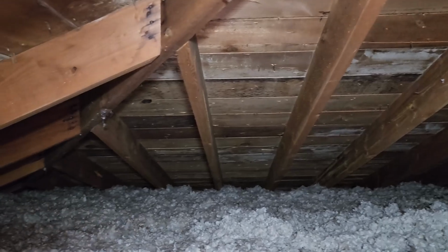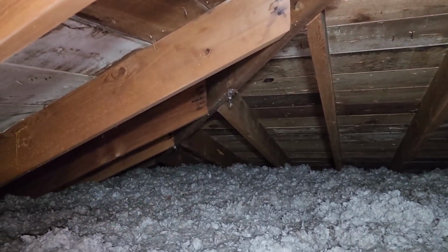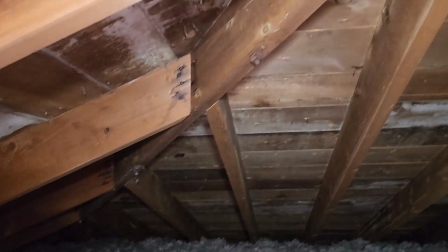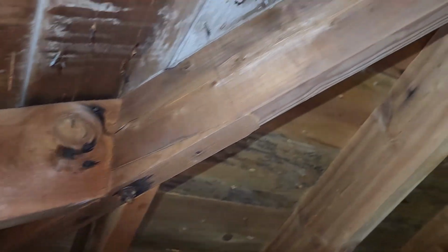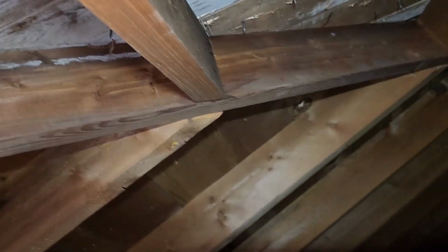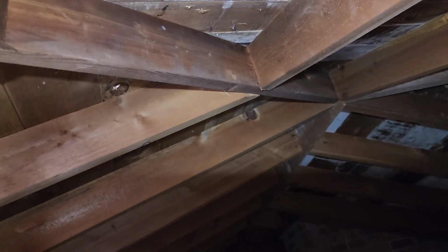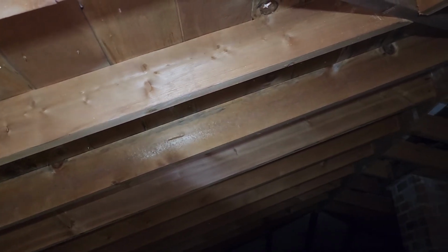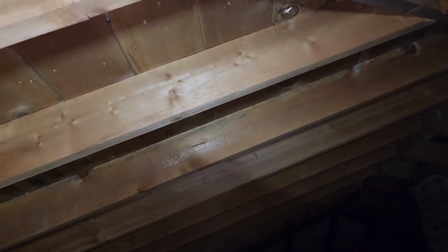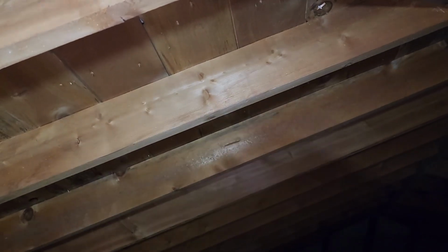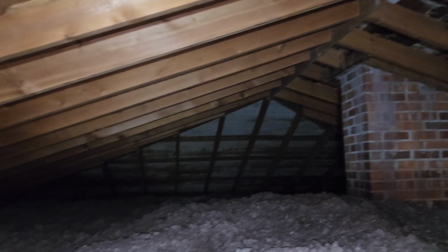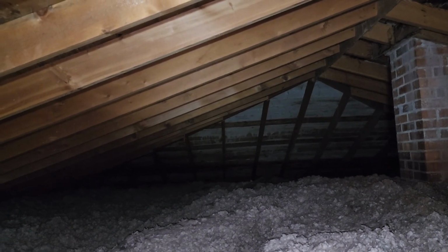Okay, so I'm looking north. This is the northwest ridge. And I have 1, 2, 3, 4, 5, 6, 7, and the 8th roof joist, which looks like 2x8 nominal lumber, goes down from a 1x ridge, looking to the east now.